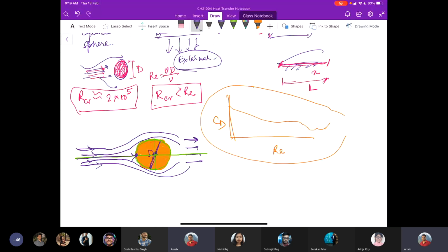This is the midpoint, okay, where the fluid's velocity is lost. It comes to a complete stop. Now, quite naturally, if the flow there completely stops, then it increases the pressure to a very high value. Okay, and pressure decreases as you go along the direction of the flow, as the velocity increases. The pressure decreases as the velocity increases.